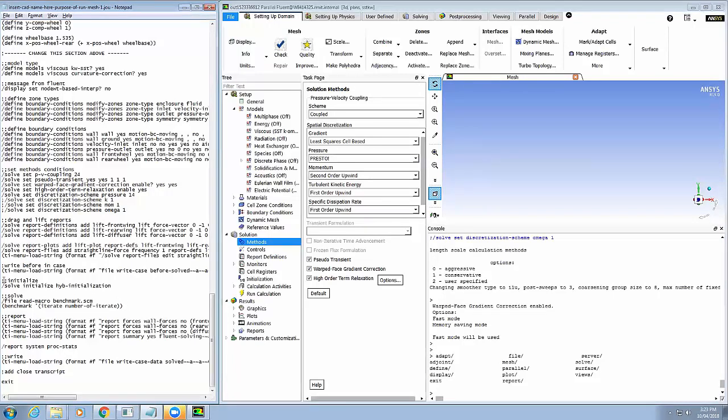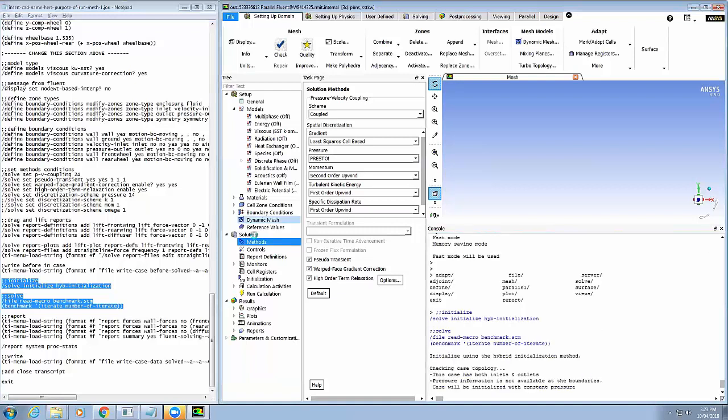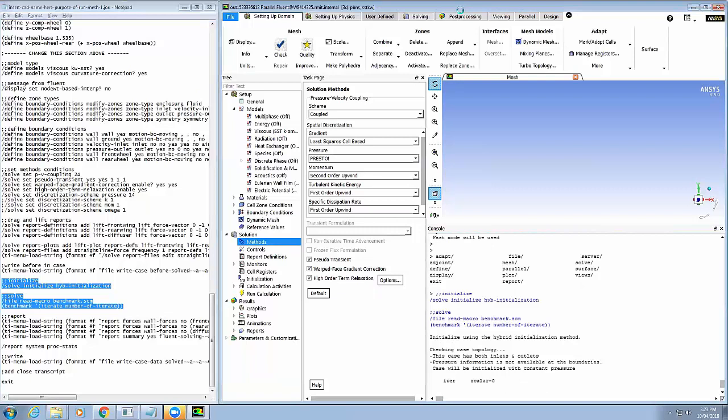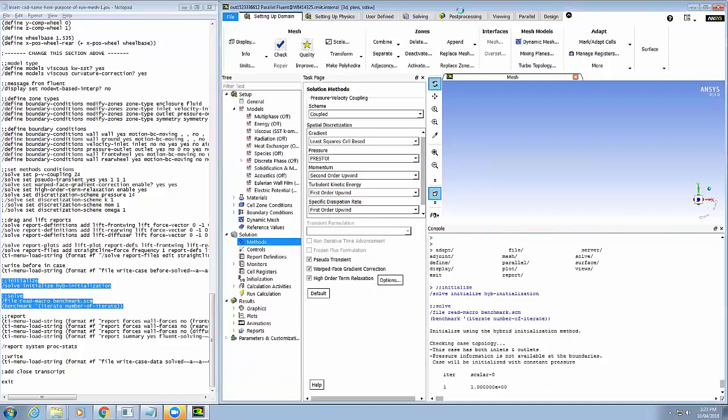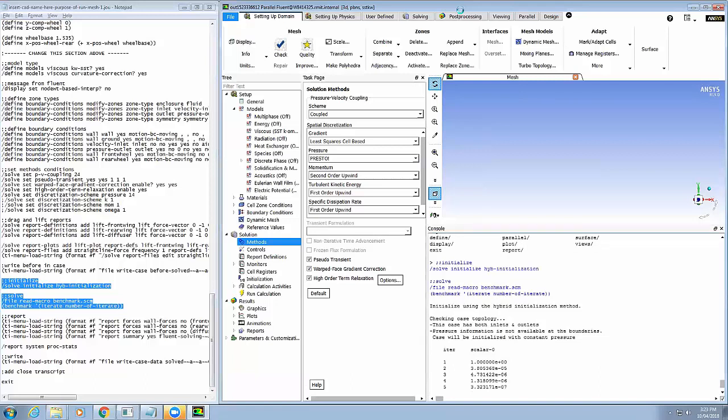All right, so let's initialize. I can usually do all this stuff without the script. It's just the meshing that's wigging me out. Oh, right. All good. So the rest of this stuff is okay to you then? Yeah, it's been fine. Doing the rotating wheels, I understand how to do it, but I haven't done it yet. You have to know the origin, your wheel's center point origin, right? Exactly. It's a rotating wall, so you need a 0, 0, 0 XYZ coordinate. You need to give it an axis, and then a rotational component afterwards.